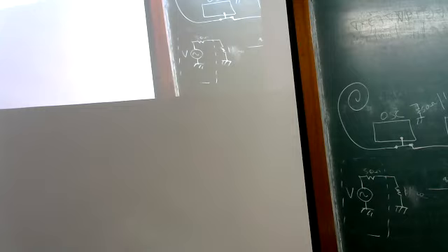transmission line. Inside this cable, there is a center conductor, which is the active part, and then the outside ground. Both this cable and this cable have the same coaxial structure, but they are made differently with different sizes. Sorry? The diameter of the cable. So both the outer diameter and the inner diameter. We will look at this in more detail in just 15-20 minutes.